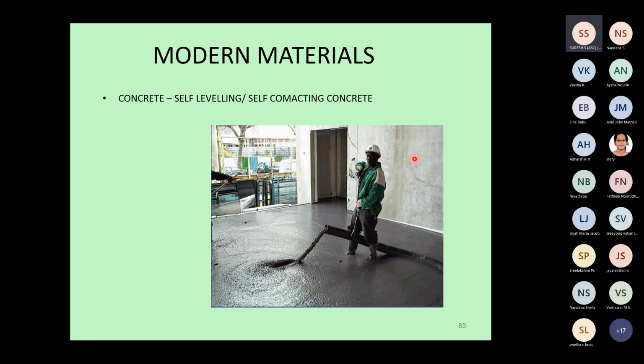Regarding modern materials in concrete, it is now very common to have self-compacting concrete or self-leveling concrete. You just make the formwork around and pour the concrete. You don't have to vibrate it because it is self-compacting. You don't have to level it because it is self-leveling. All these things might be in your concrete technology, and theoretically we can study them in books, but making them is an art rather than a science. You need to make so many trials before you can realize a self-compacting or self-leveling concrete at site.